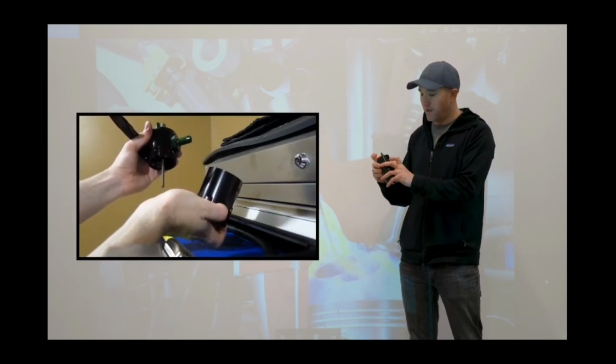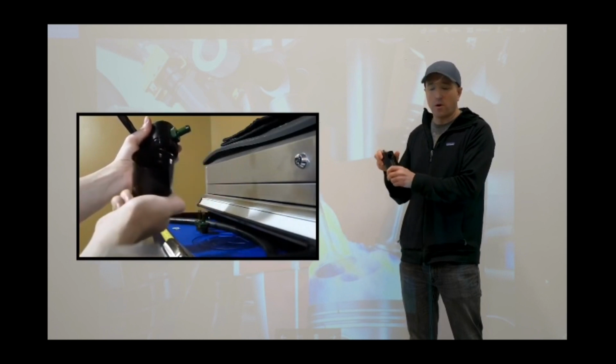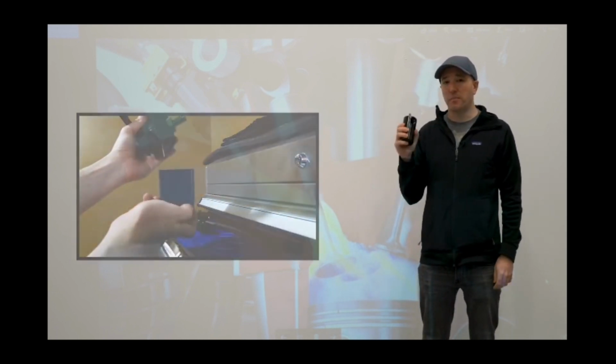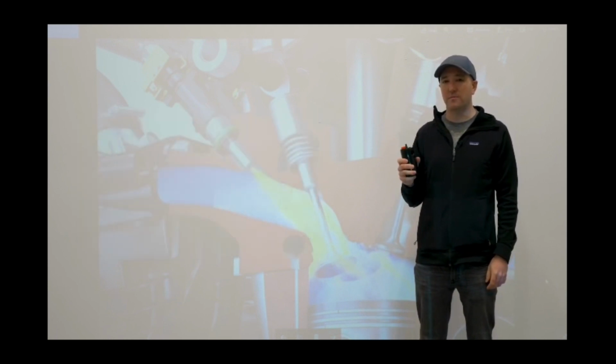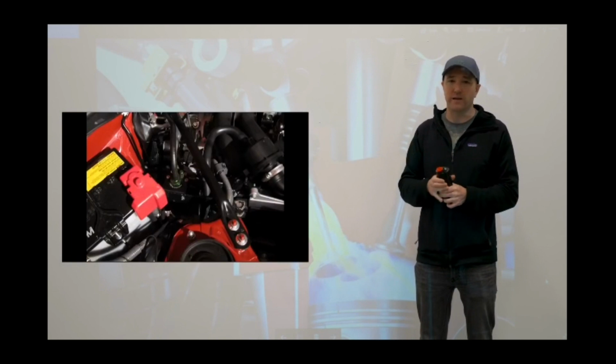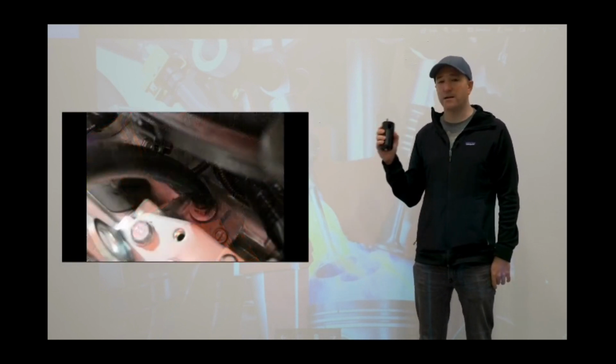So you need either a scrubber or a baffle inside to separate that air and oil. Now, some manufacturers are putting air oil separators into their PCV system, and it doesn't completely remove all of it. Just like this, it's not going to completely remove all of it, but it's going to remove 95+% of it.